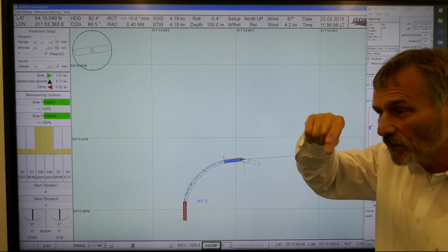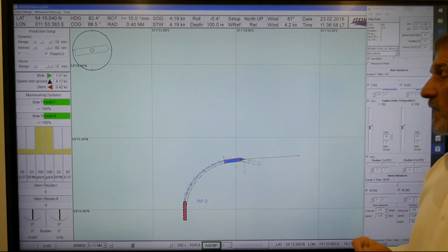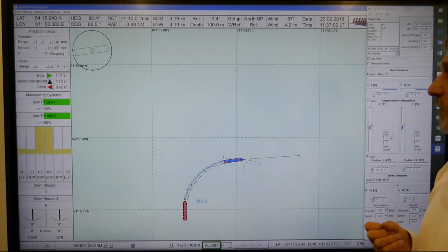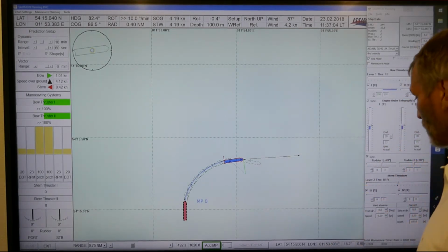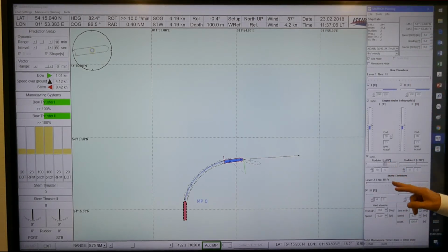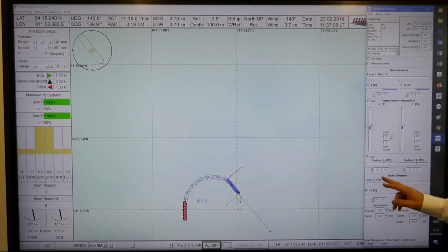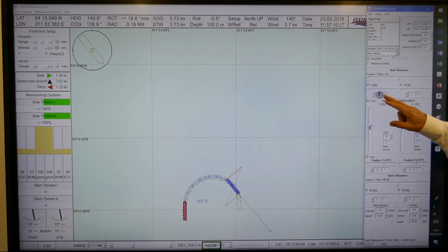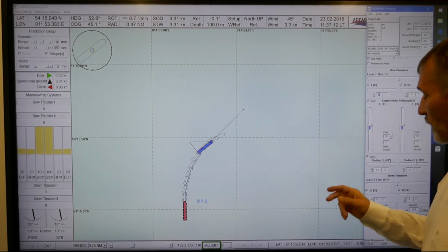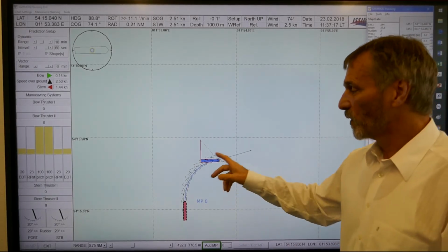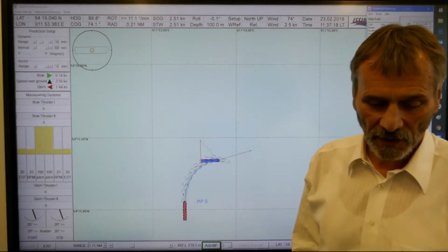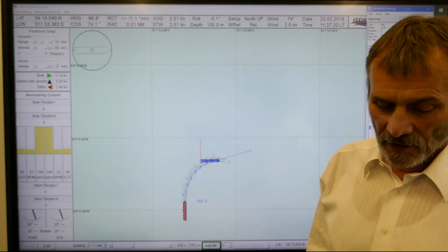If you want to really be using only a small maneuvering space, then you should better go with your bow thruster instead of the rudder. So again, if you use the rudder instead and no bow thruster, then you see the swept path, because of the drift angle, is much bigger.